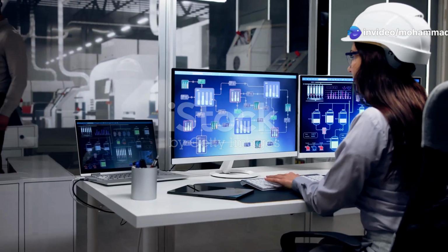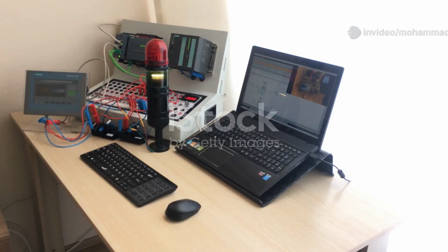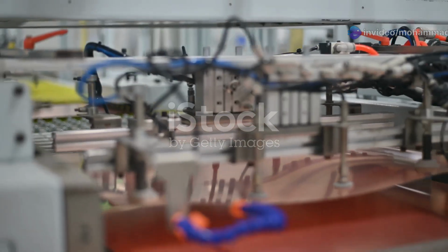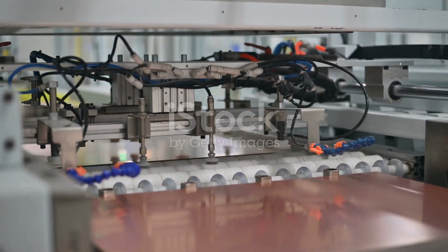Programming a PLC is akin to teaching the orchestra conductor a new musical piece. We use specialized software and programming languages like ladder logic or structured text to define the logic that governs the system's behavior. This involves configuring inputs, outputs, and the logical relationships between them. Let's take the example of programming a PLC to control a conveyor belt with sensors and actuators.